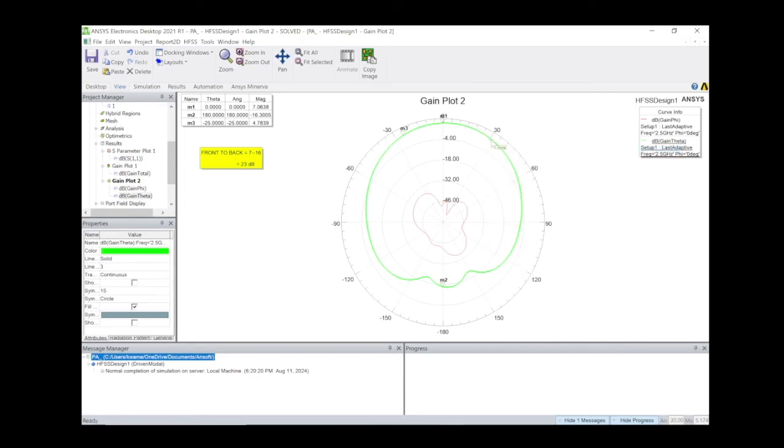Okay, so this is it. We have 5 point something over here. We have 4.4. So 4.4 is fine. So you will subtract. You don't have to subtract. So just insert and dot. You say half power beamwidth should be equal to 35 degrees minus 25. So we have 60, right? So that will be 60 degrees.